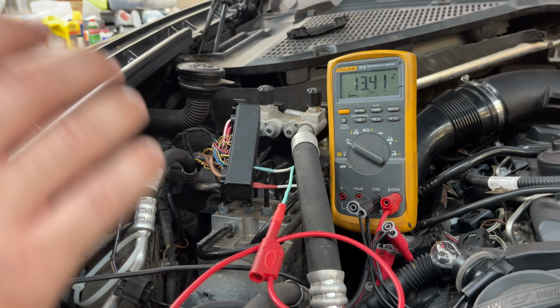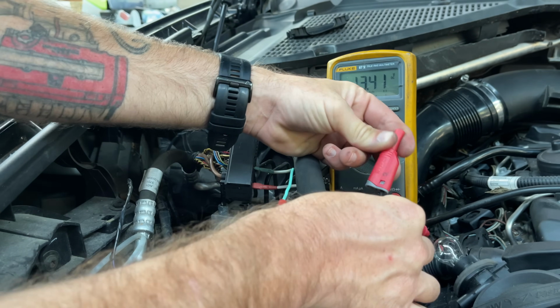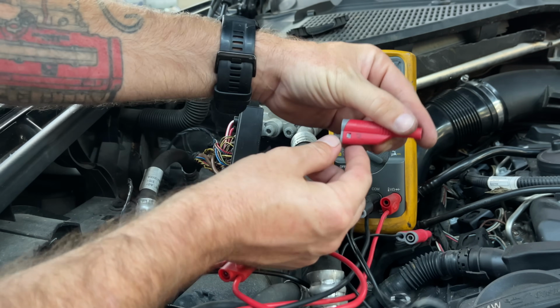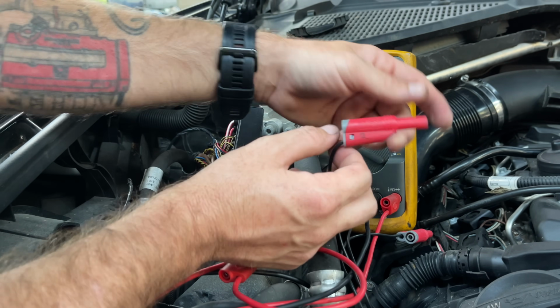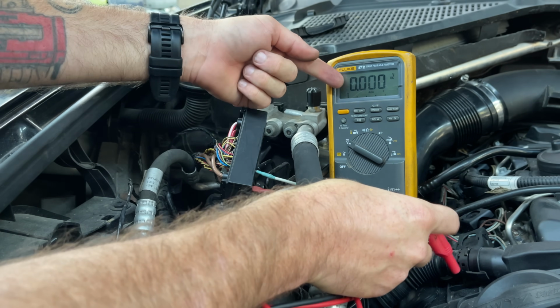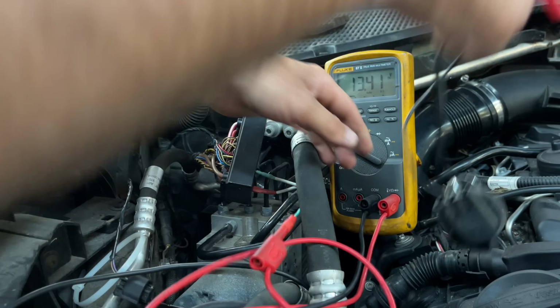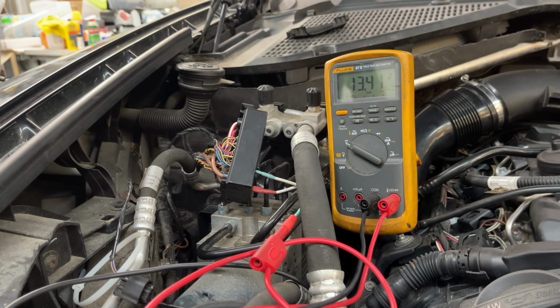So it depends on what bulb you're using. That was a 2 amp filament. Don't know if you guys can see that, 2 amp, where I have it written on here. If I go to my 1/2 amp, you can see my voltage still goes away. So let's change to a different bulb, or different test light.